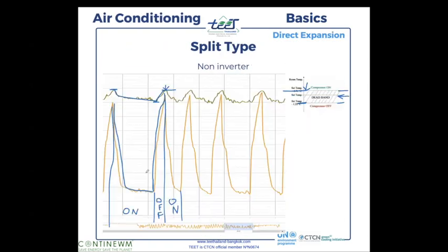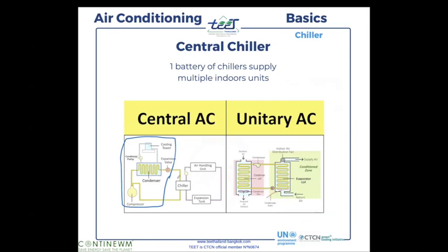In a chiller, here we have the condenser, the expansion valve, the compressor, and a refrigerant fluid, but the evaporator, that I will name E, instead of being directly in the air, is inside water.